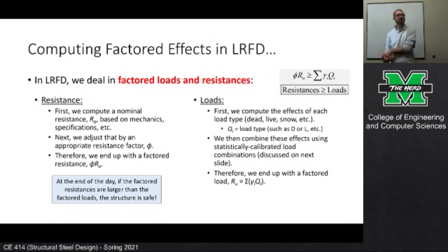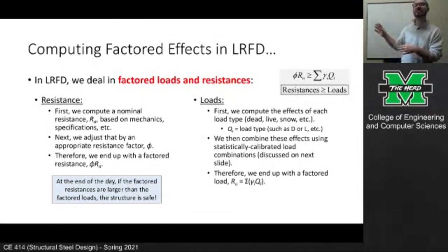And then we do the same thing on the load side. We have all these different load effects like dead loads, live loads, snow loads, wind, etc. We combine those using these statistically calibrated load combinations to get a factored load. So we're comparing factored loads and factored resistances.